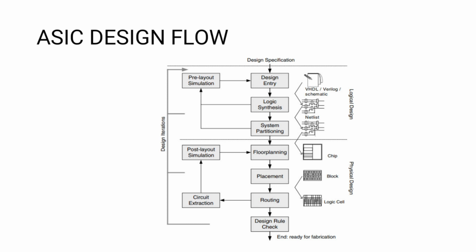Next we go for the physical design. Floor planning assigns each and every component inside a chip. Then placement gives the accurate places where we need to place the components nearby, and how much gap will be there. After that, routing: the connections between the blocks happen in the routing.